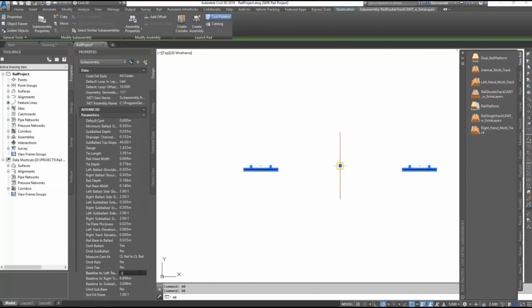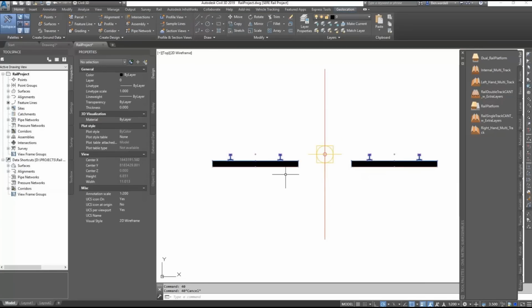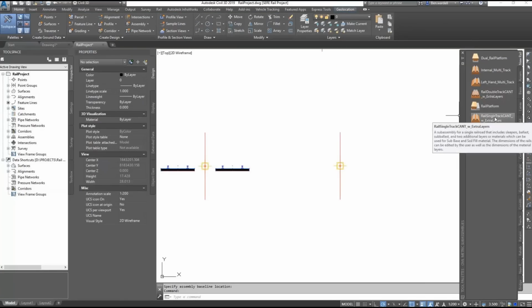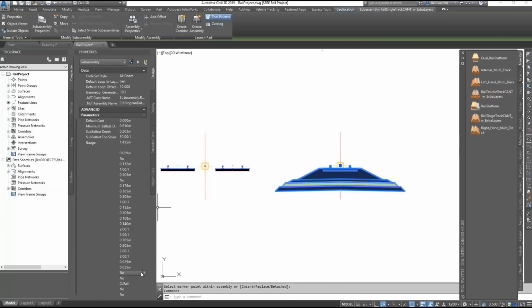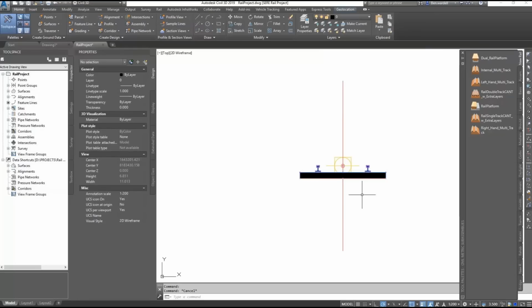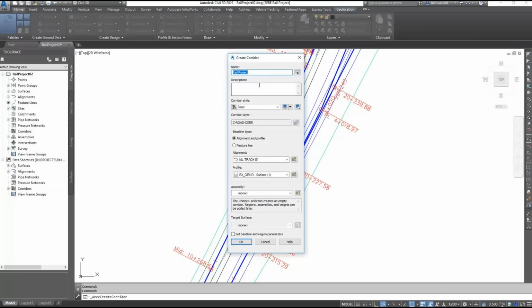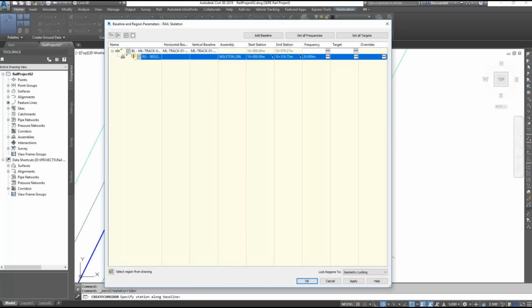In this particular model, we're just going to run a skeletonized track. And these assemblies, the way that they're set up, all I have to do is tell it to turn off ballast, and the only thing that it'll give me is the rail and the ties or the sleepers. It's doing the same thing here, omit ballast, and just say yes, and now I'm just going to run this as a skeletonized track. That's kind of typical when we're modeling something that is an existing condition and where we may have just some general realignment, and maybe they're going to come in with ballast later on after the track has been realigned or shifted one way or another. But this gives us a good model that we can kind of work with.